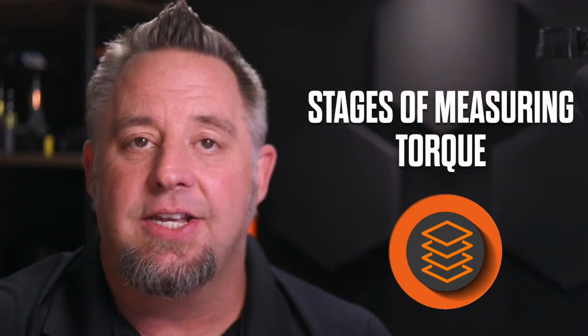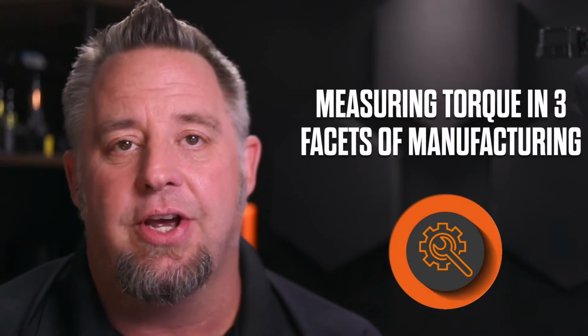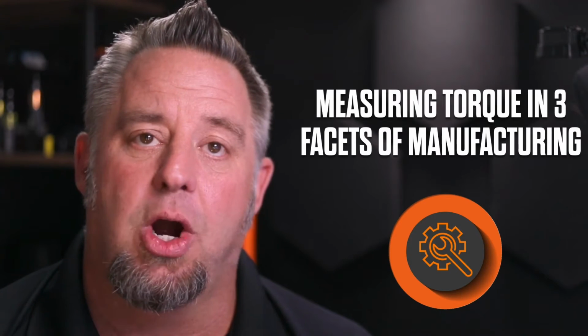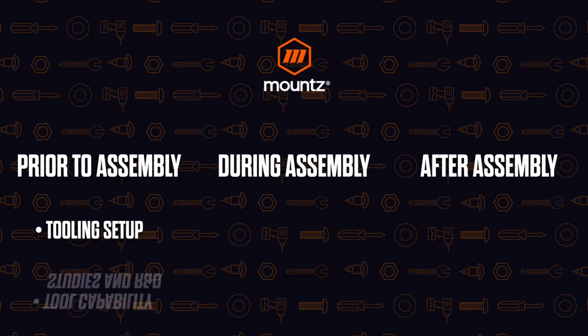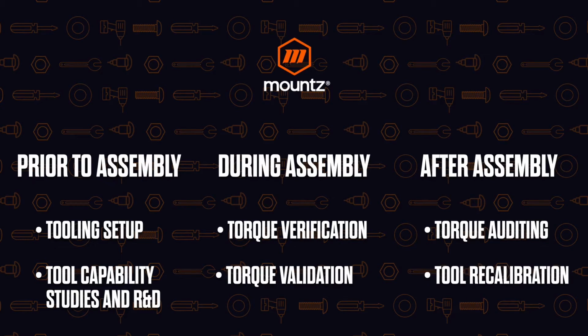And so when we look at the different stages of measurement within the assembly process, there are basically three areas of manufacturing where we can do measuring for our tools and our torque. That's going to be prior to the assembly process, during the assembly process, and then after the assembly process. So when we look at prior to the assembly, we're looking at testing our tools to be able to set them up on a torque analyzer, so we can make sure that those tools are repeating correctly. We could also do tool capability studies for our R&D processes as well. So if we need to develop a torque specification, we would be doing measurement before that.